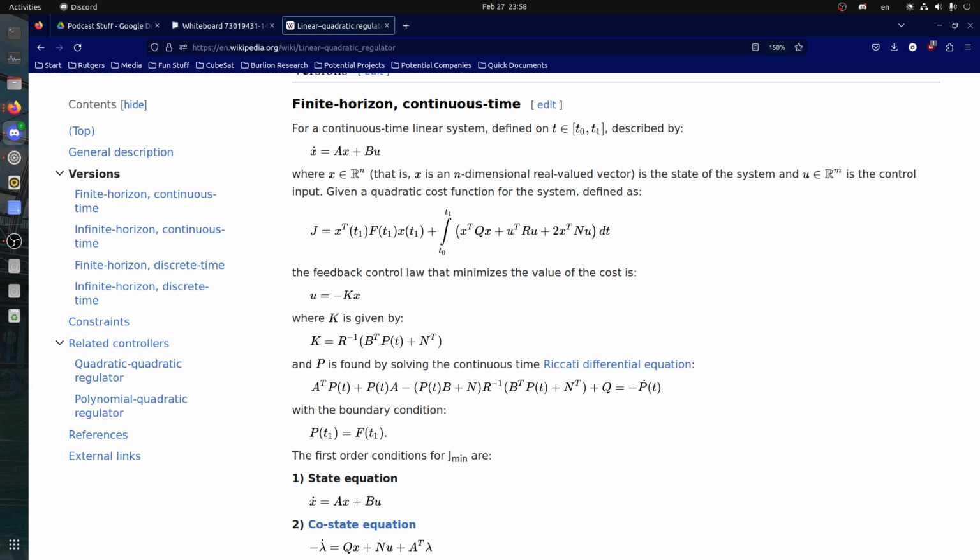If you had an infinitely powerful reaction wheel, technically you could do it in a split second, but that's a ton of electricity that you have to pump in for a very small amount of time. So there's a cost to using a large reaction wheel in terms of energy. And then there's a cross-coupling term, which is where you are plus how much energy it's taking. And what the linear quadratic regulator does is it optimizes this, or rather it minimizes this.